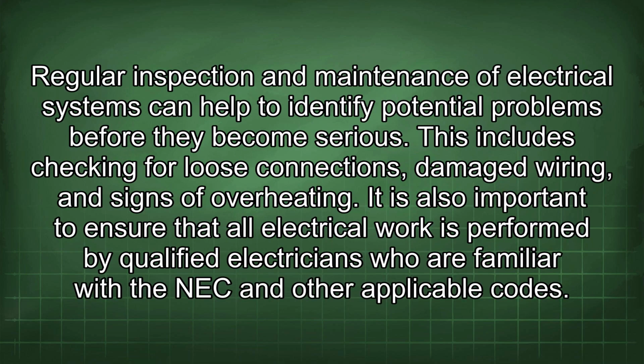Sixthly, maintenance and inspection is critical. Regular inspection and maintenance of electrical systems can help to identify potential problems before they become serious. This includes checking for loose connections, damaged wiring, and signs of overheating. It is also important to ensure that all electrical work is performed by qualified electricians who are familiar with the NEC and other applicable codes.